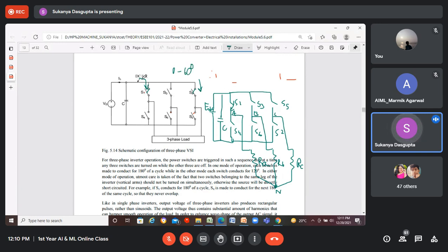That means current is flowing through this. So this should be opened because it's a complement of SW1, like this, that is coming to this neutral point. And also current is flowing through this switch because switch 5 is also forward biased, since current is now flowing. So this should be turned on. So current is flowing through this switch, so this is closed.